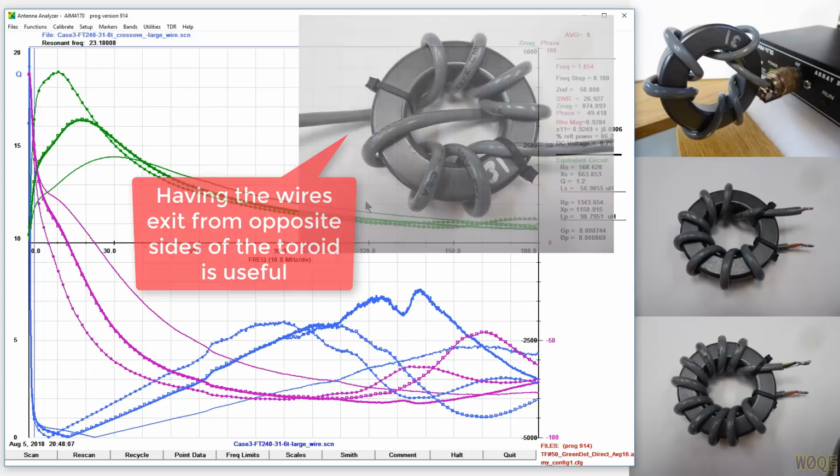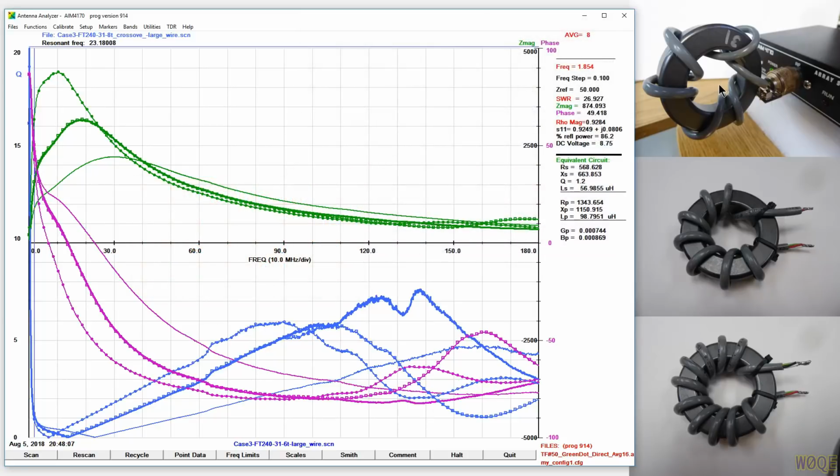It seemed to me that if you're concerned about the higher HF range, you're better off with 6 turns. Lower HF range, 11 turns, somewhat over the whole band.